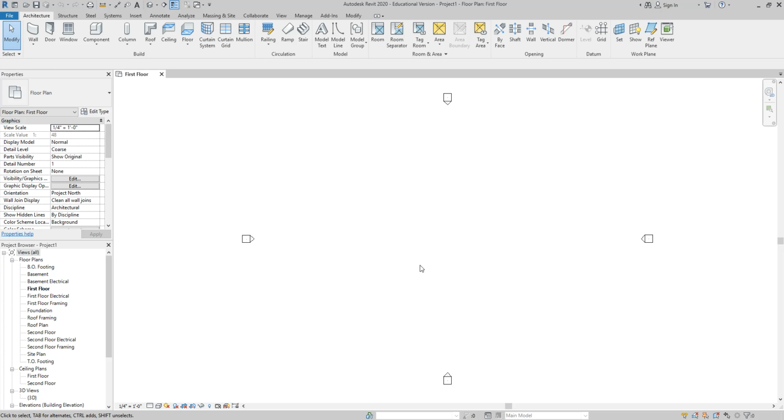Or you could be working with an architect who only works in AutoCAD, and you might be doing your work in Revit. That happens to me a lot too. Other architects, if I do a tenant finish, may have designed the entire building or the entire complex in CAD. They give it to me in CAD and I just overlay my Revit file on top of it. So it's a really nice way to trace out your plan.